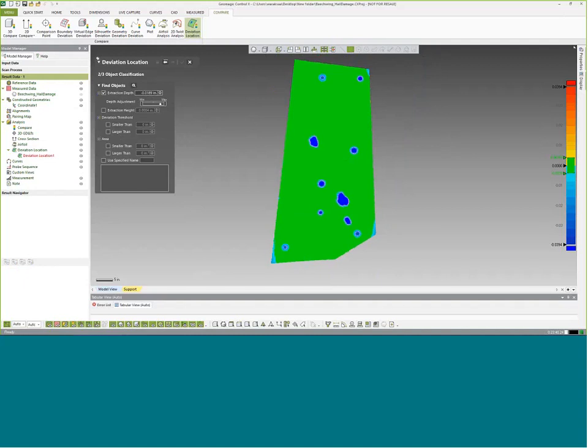So right now we're saying that everything that's basically 20 thou or deeper is being outlined. Maybe we want to increase that a little bit more. Maybe we want to say, hey, let's go up to something a little more reasonable. We'll do something like 50 thou. And make sure to see if anything's further down than that. That'll be our things of interest. So you see automatically it got rid of a couple things that were very shallow on the surface here. And it highlighted everything else, gave them a nice little tag here just to let us know what it's doing.